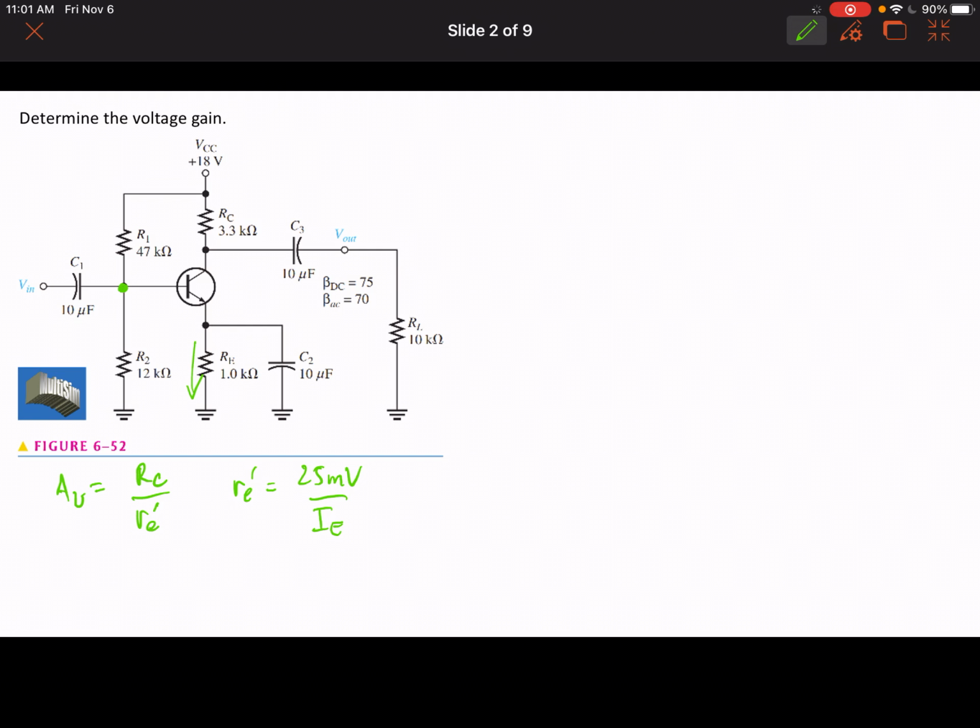It's always a safe approach because you don't have to think about whether the input base resistance is comparable to the other parallel resistors. So just to be safe, you can simply use the Thevenin equivalent resistance to solve for the bias.